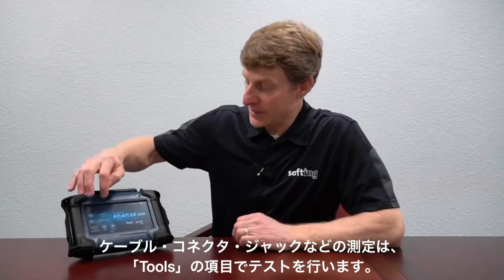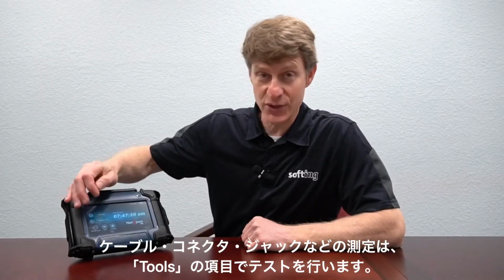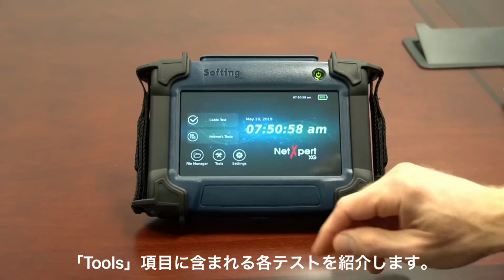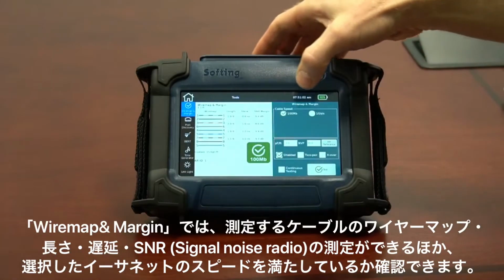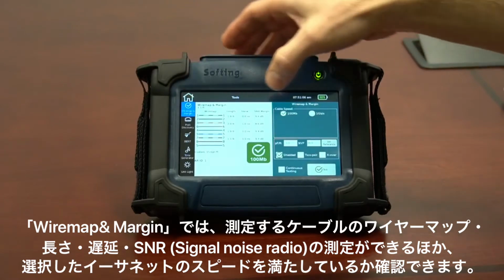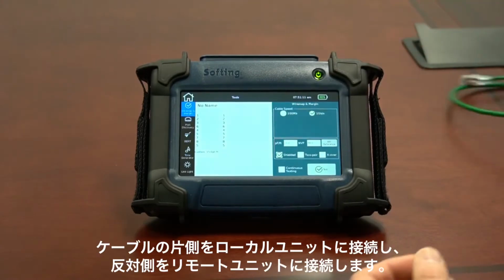So the way you do this is you'll go to the Tools section of the NetXpert XG just to run the individual tests. So let's run a gigabit per second test on our cable to see if it'll perform at the speed that we need it to perform. So I'm going to select Tools. I'm at the wire map and margin test. I'm going to select 1 gigabit per second.